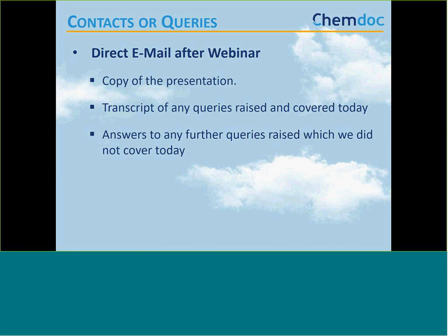So if anyone wants any more information on that, you can just drop me a quick email. There's a segregation table that I can send you that will show some of the classes that you shouldn't store together, etc. So the point is, before I even look at signage, I would look at segregation first, and look at what is segregated where, what should be kept away from what, store according to that, and then look at your signage and make sure that there's signage up to very clearly show what chemicals are in different cabinets.